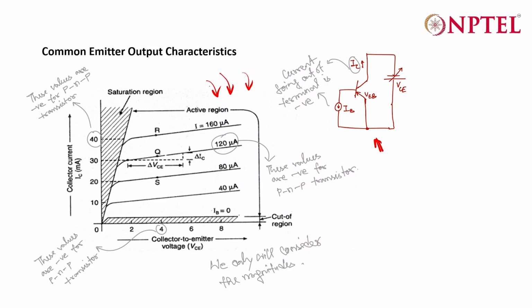configuration. So you have collector current and you have collector to emitter voltage. Now, in this case, you can see that initially the relation between the output current and output voltage is linear, and then the current will kind of flatten and sort of saturate. So it's not exactly saturating, it's not constant. There is a slope associated with that, but it's sort of saturating.